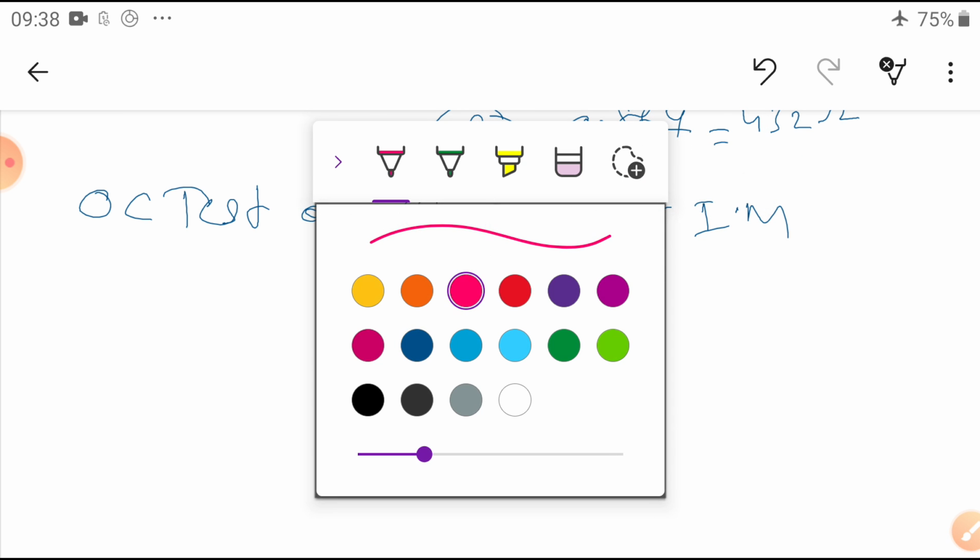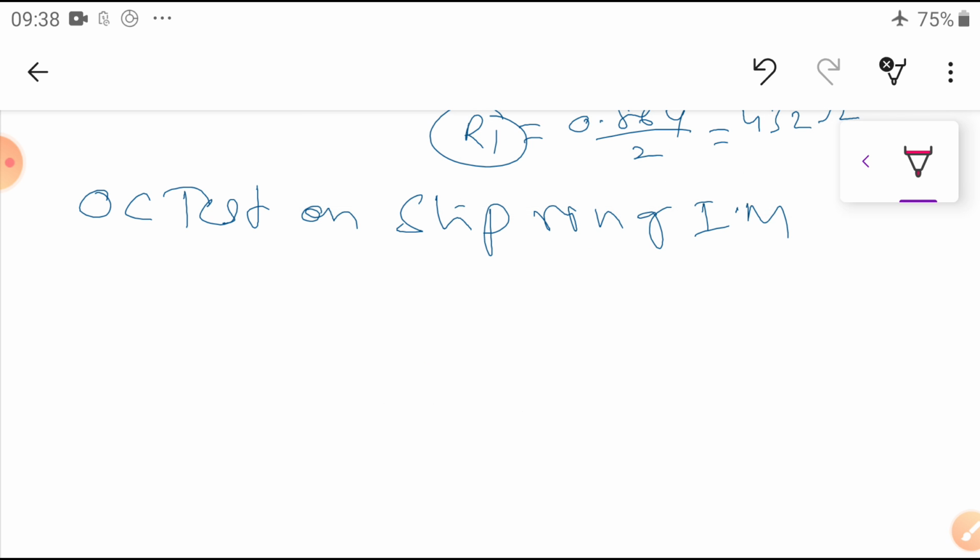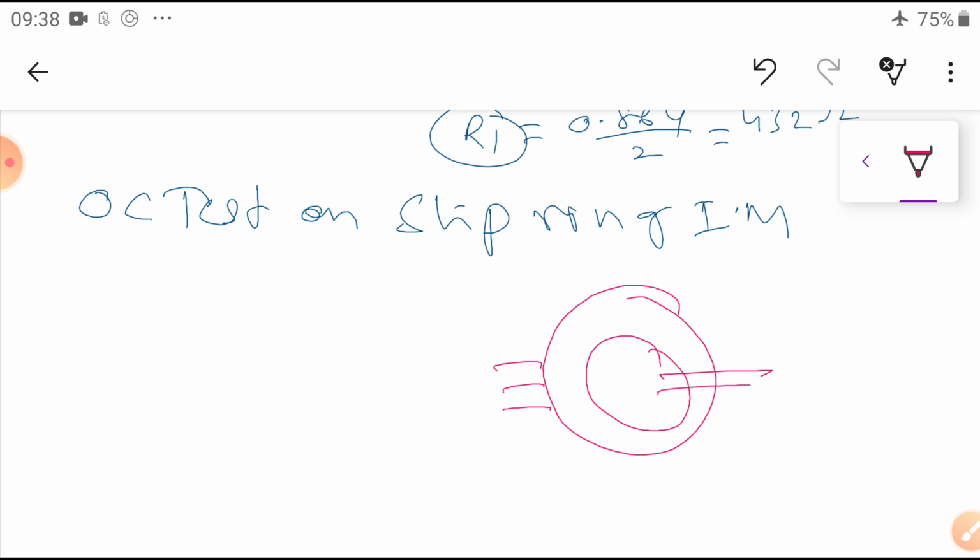Now, same thing. What has happened? On the stator side there is a 3-phase current, and on the rotor side there are 3 windings. So what will happen? You start the rotor and keep it in the running position. That means these 3 are simply shorted, with no resistance added in the rotor circuit.